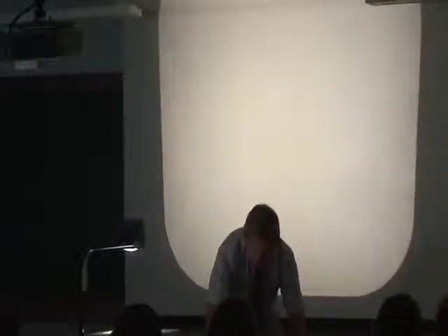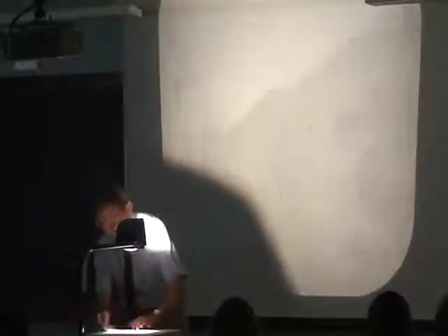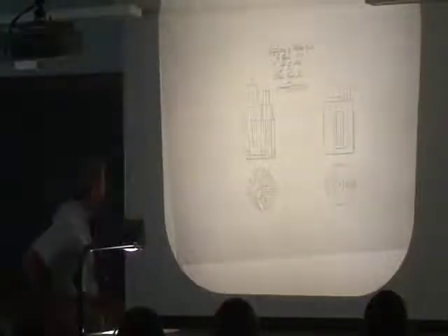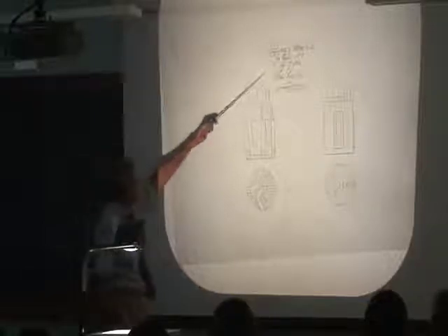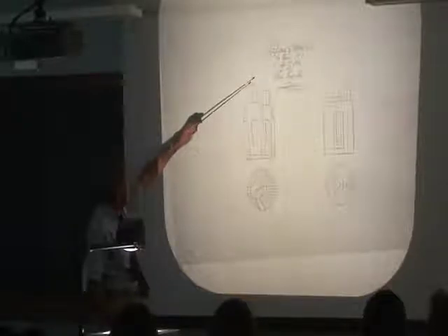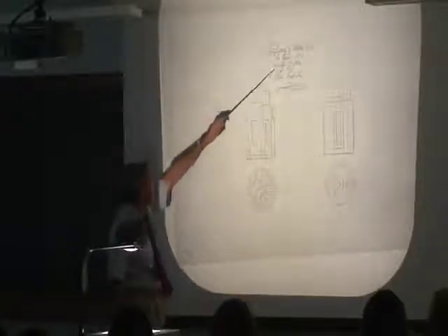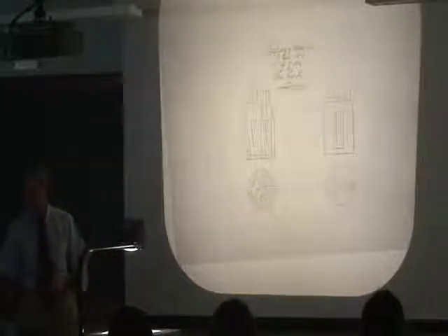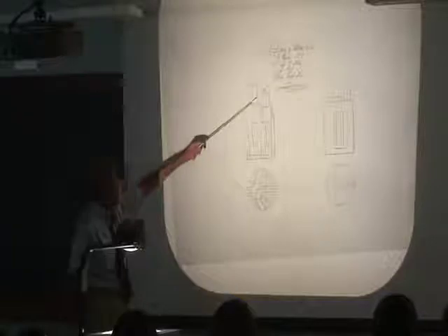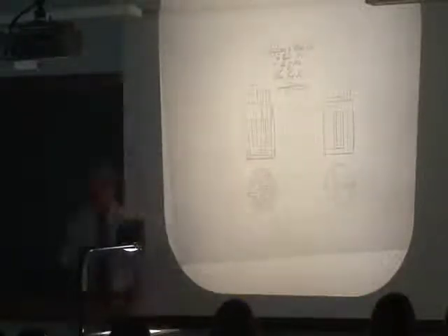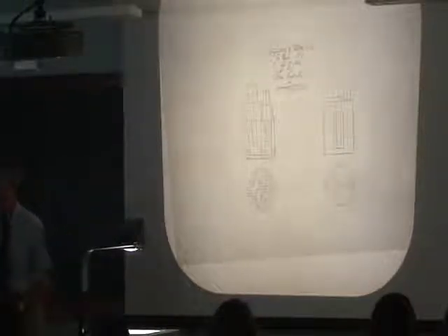Remember the locomotive we had up a while ago? This is one of the components in the locomotive. This is a beautiful longhand script. I doubt if you can read it. It says this is a regulating throttle cock. What that means is it's the valve which controls the steam flow to the cylinder. And the date on it is 1804, and it tells you the scale is half size. That is the complete definition of the part.